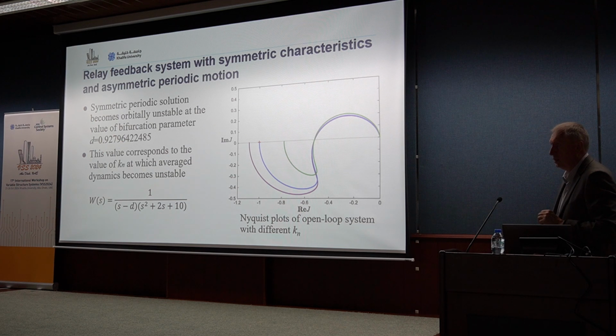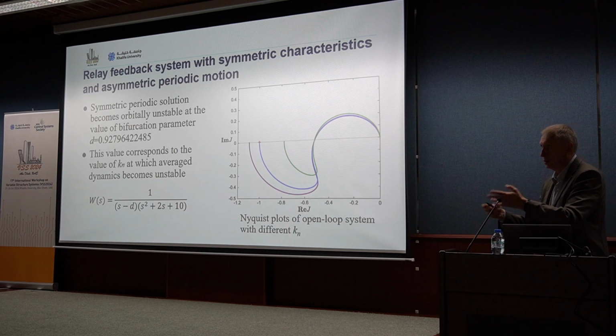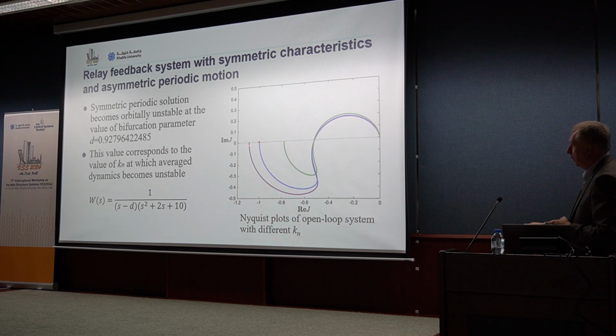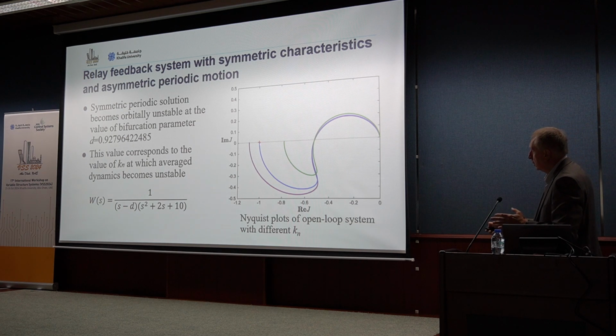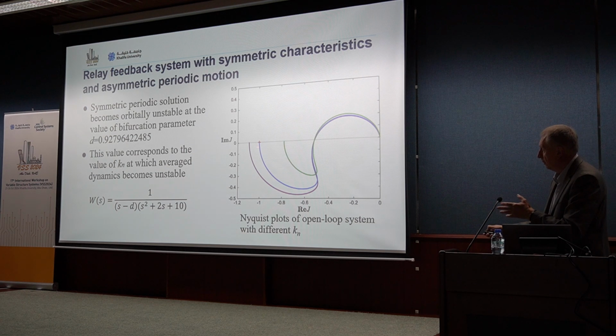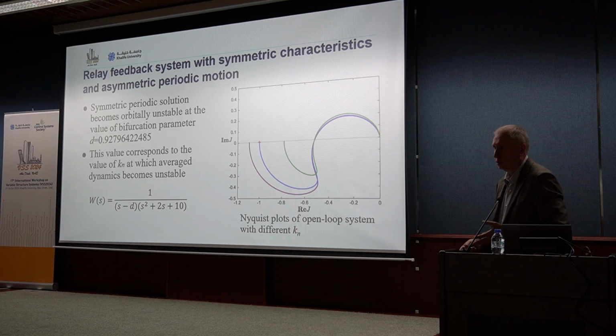So it's exactly these values with this number of digits, because this blue line, this is -1 and 0, the critical point of the Nyquist plot of the linear part, which includes Kn, and Kn is found through finding of the periodic process and the LPRS. Here we have an unstable linear part and a stable linear part, and as a result, whatever is right of this point, we have a stable symmetric limit cycle. Whatever is left, this limit cycle is not possible.